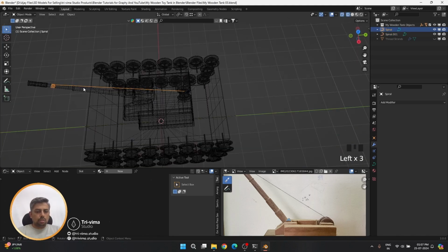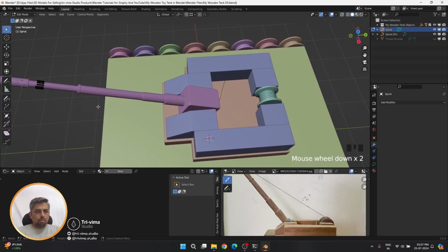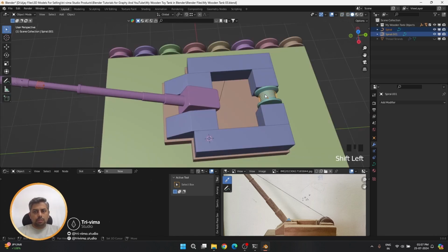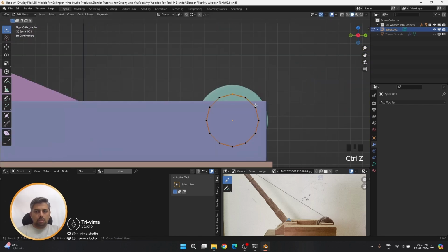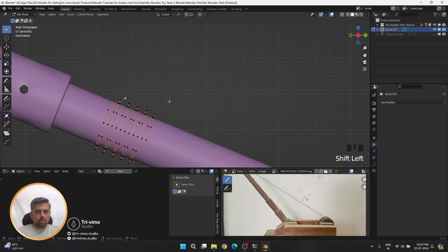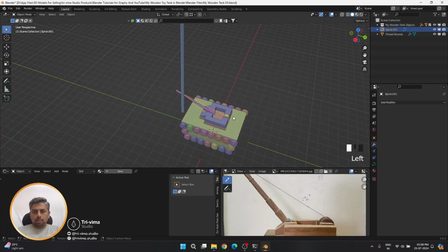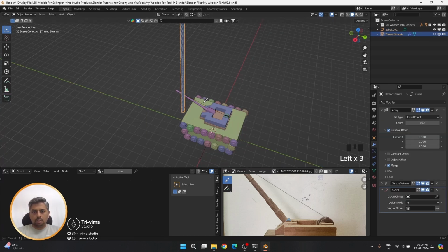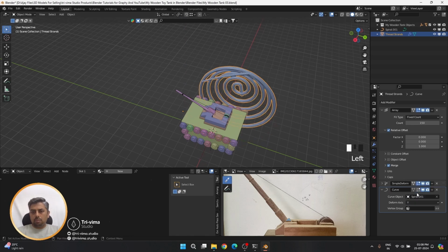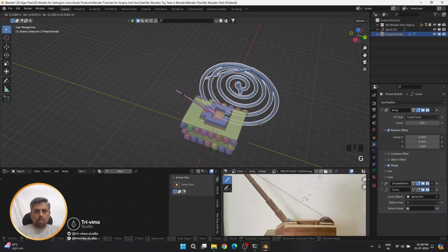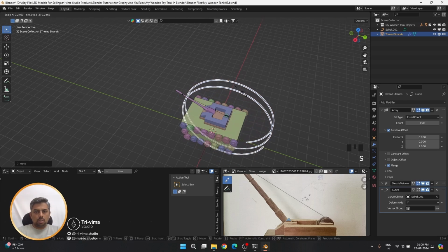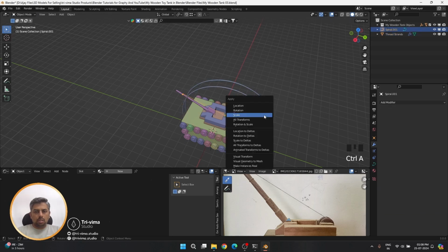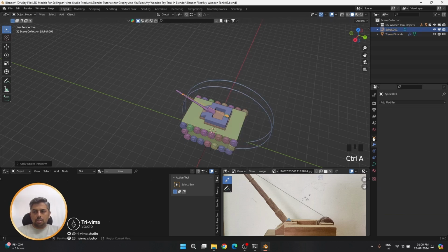Now what we will do, this one, and say delete vertex. So now selecting these, Control J. Now I will connect by this vertex here, again here, yes, from this to this connected. And let's see now on this curve. I will pick this, and I'll split this curve. Okay, now again the y-axis. Scale it. Okay.